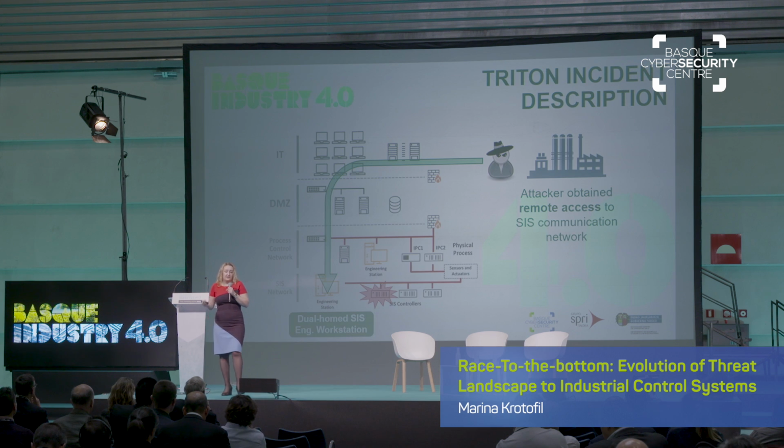A short summary of what happened: the attacker obtained remote access to the safety instrumented system, and there was a dual-homed safety engineering workstation, and through that the attacker gained the capability to interact digitally with the safety controllers.